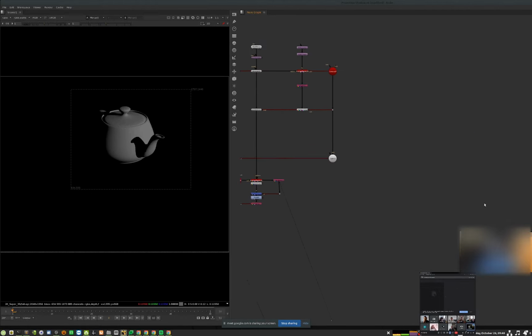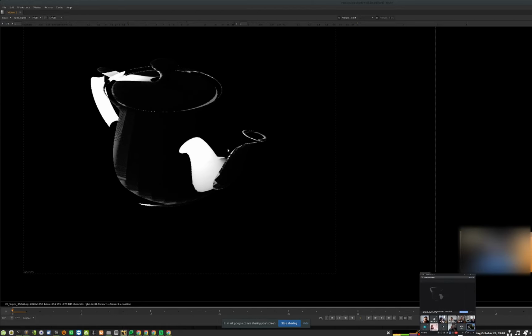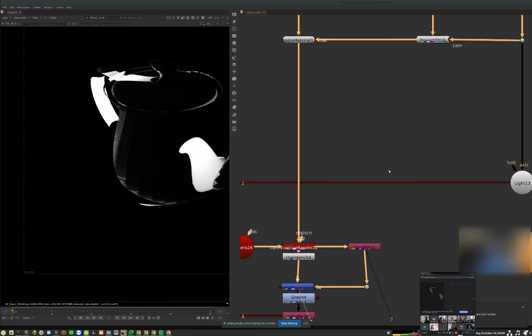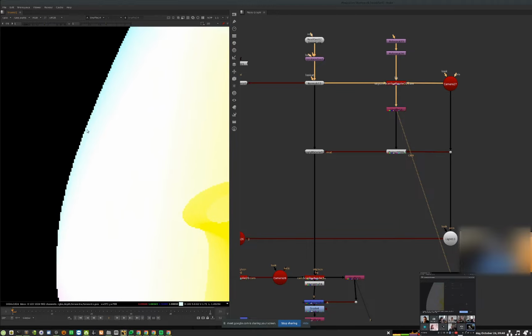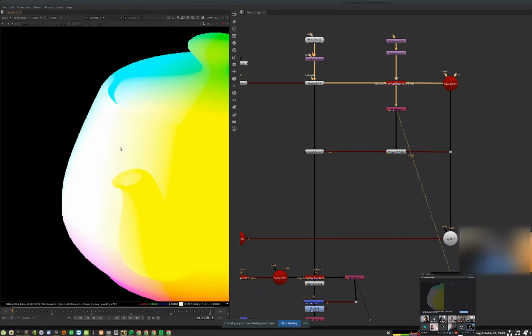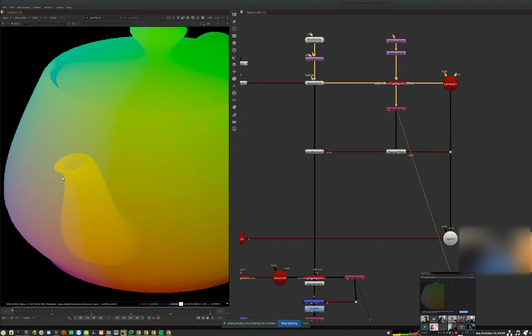There is a limitation to this, as you can see. If I show over here, the areas that are getting on the most side planes of the projections from our camera projecting point, which is actually this area of the teapot, and this area, are getting a lot of errors. It's a floating point error, a filtering issue, because if you think about it, we are taking these elements and projecting them on the polygon. So it means some polygons would fall between those points, so it will not actually give us the right position area. So everything at a grazing angle, which is this guy over here or this teapot over here, will give us all this messed up area.